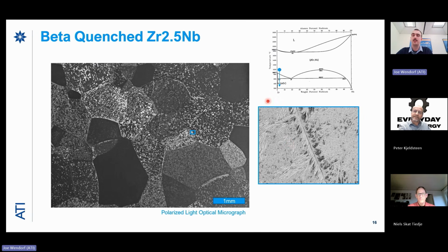It's helpful in the extrusion process to have the niobium supersaturated in the alpha phase, because then we can control the extrusion process to pull that niobium out in a controlled way, as opposed to having those really large clumps of the beta phase in the as forged structure. Okay. Yeah. Is it cold extrusion, or do you extrude at 400 or 500 degrees or something like that? I can't share the exact temperature, but it's in this triangle here. All right. Yep.